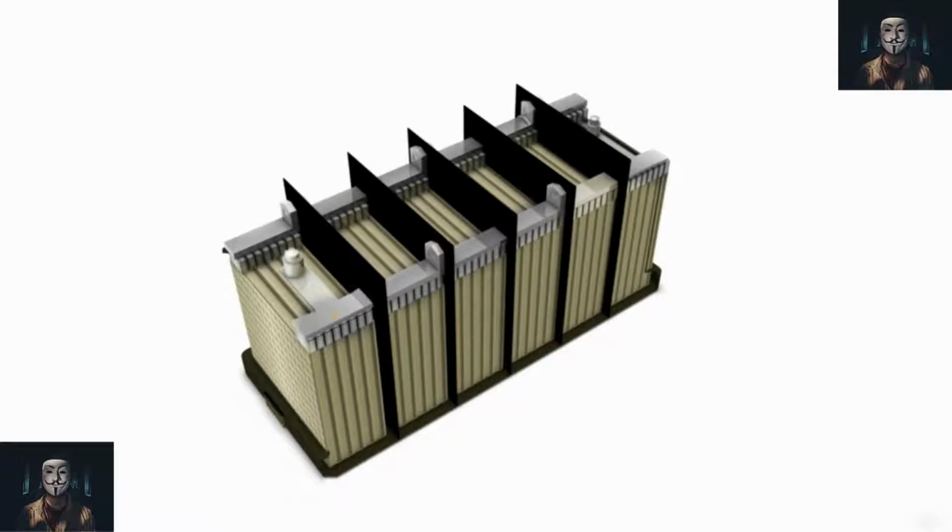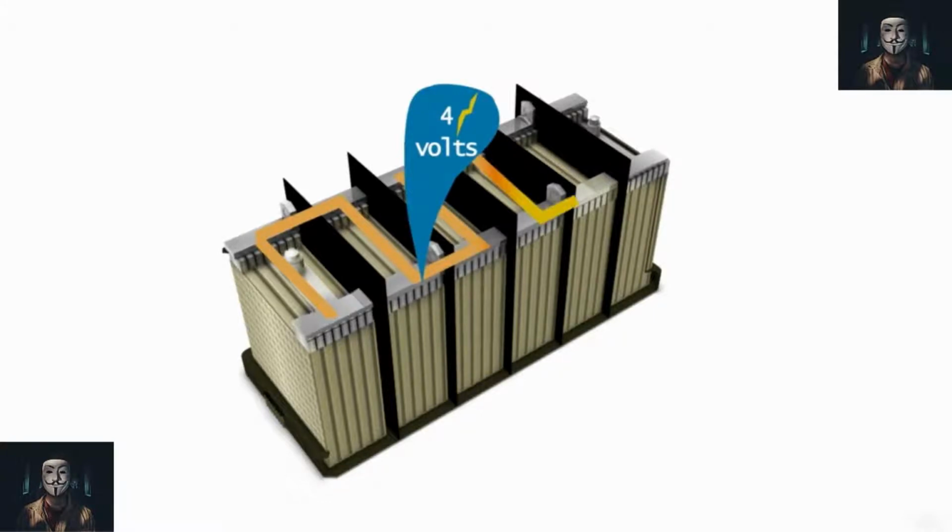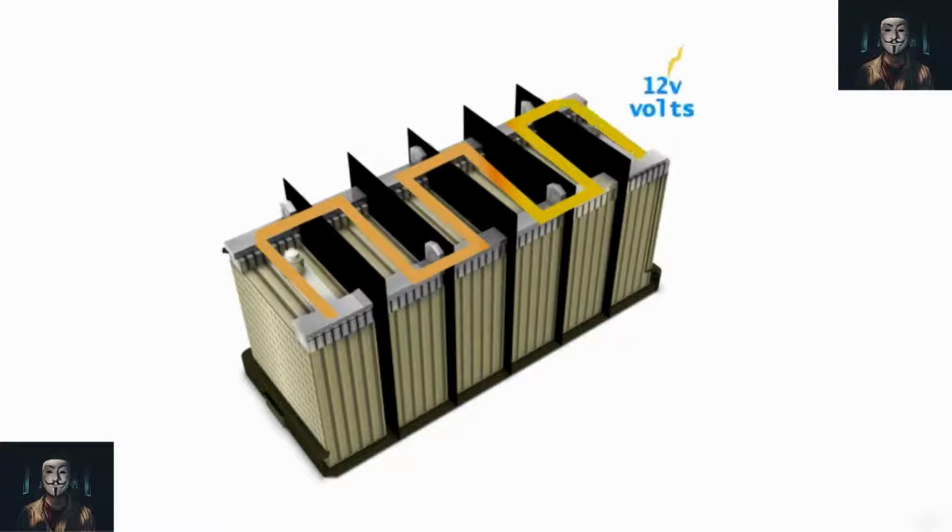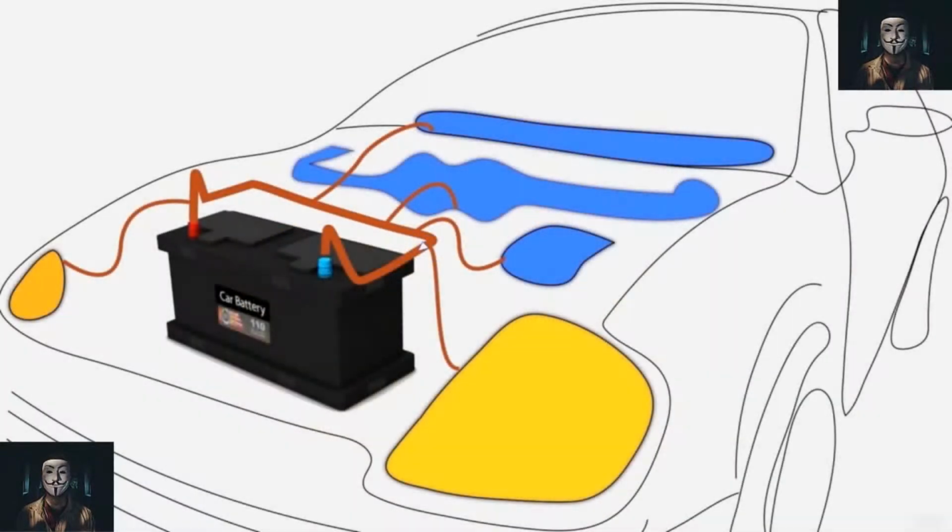Applying an electric current to the battery reverses the process. The charged battery stores chemical energy. This can be released as electrical energy when the battery is connected into a circuit. The electrolyte is dilute sulfuric acid, which reacts with the cell's plate material during charging and discharging of the battery. Sulfuric acid consists of hydrogen, sulfur, and oxygen. These chemicals separate during the charge and discharge process and attach to the cell plate active material or return to the electrolyte.